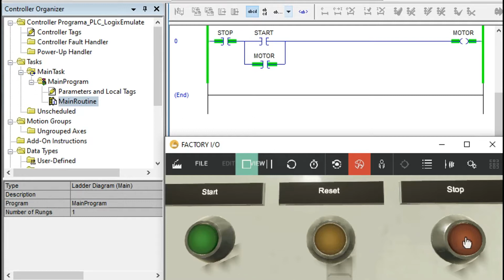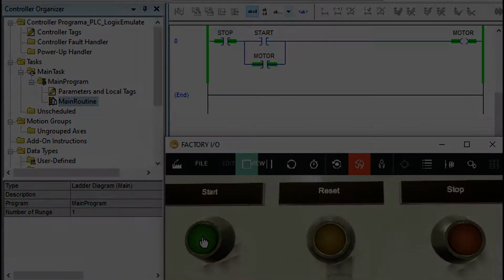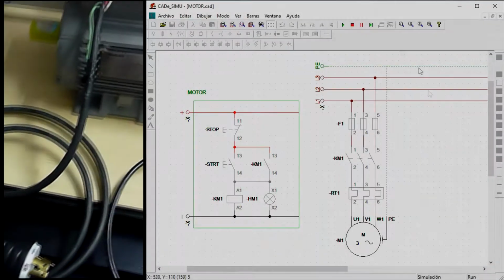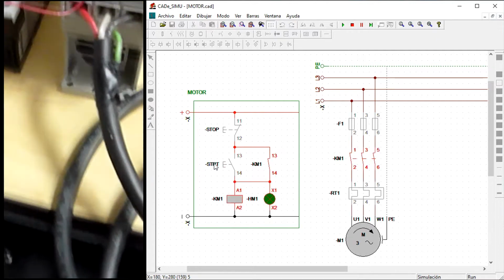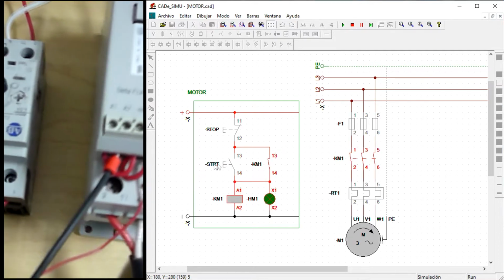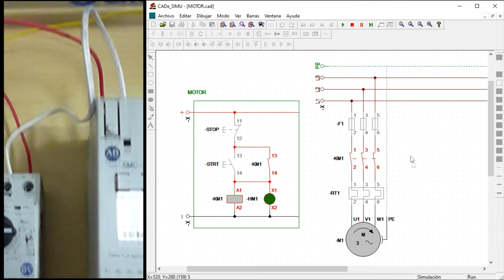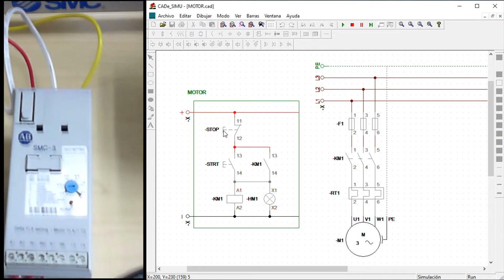Since the communication between the PLC and the programming software is carried out by TCP connection, a new element can be added, the digital twin. The digital factory and the physical machinery can send and receive control commands to the IP address of the PLC. This allows the interaction between a physical PLC and a virtual plant. This data management can be extended to a SCADA supervision system.